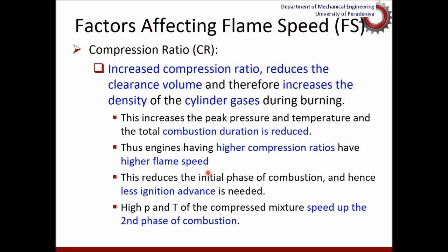That means it shortens the ignition delay so that you could initiate it close to the top dead center of the piston when it comes through the compression stroke. Therefore, you could produce more energy, more work within the engine cycle. So I will explain that again with some pressure volume diagrams later.